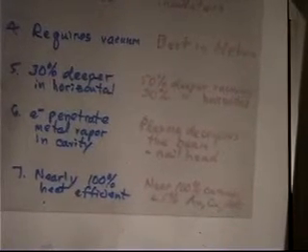It turns out with the laser, you get about 50% deeper penetration in a vacuum, a little bit better, and about a 30% increase in horizontal. If you were to use the out-of-vacuum electron beam, you're going to find one-third less penetration. So really, there's no difference here in how they behave. It really has to do with the fluid flow within the weld pool.